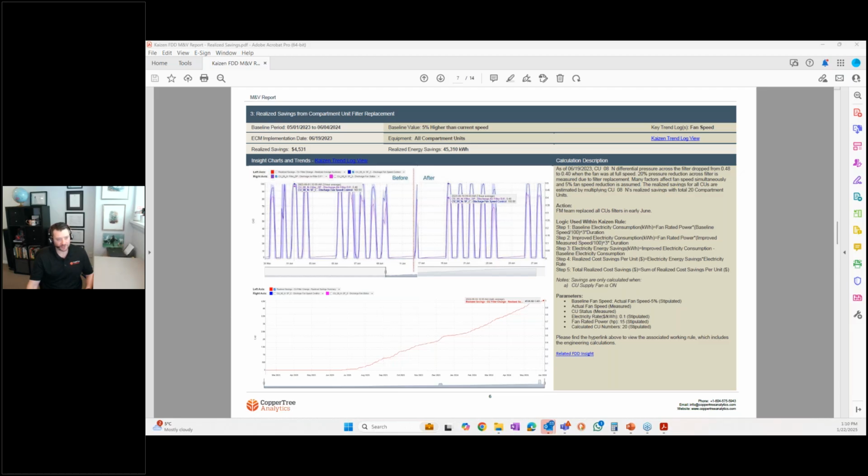Okay, I think that was the last of them. There's a bunch of questions here maybe in the chat. Maybe I'll just go look through those. For ACX, to what extent can your service verify that sequences of operation have been properly programmed? Also, what are the current limitations of your ACX service? That's a good question. So yeah, we can essentially mimic the sequences. We would look at sequences both on the primary equipment and on the secondary equipment. The limitation being that it has to be BACnet. We have to be able to write to outputs on those secondary pieces of equipment. I'd say those are a couple of limitations. Right now, as per Mike's question, we need it to be cloud connected. So we need some interface with the cloud, so some ports need to be opened, et cetera.